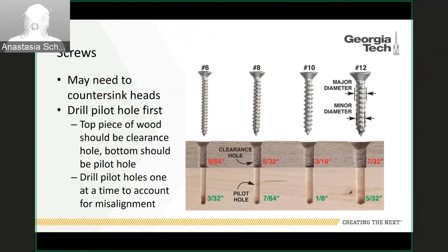When you're using a screw, you always need to drill a pilot hole before you put it in. In this example, you can see the two pieces of wood that you're trying to join together. The top piece of wood is going to have a clearance hole, so you can stick the screw through the clearance hole and it'll slide freely. The bottom should be the pilot hole.